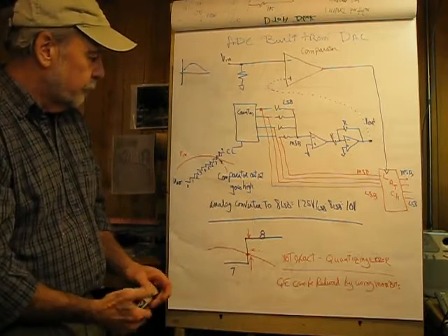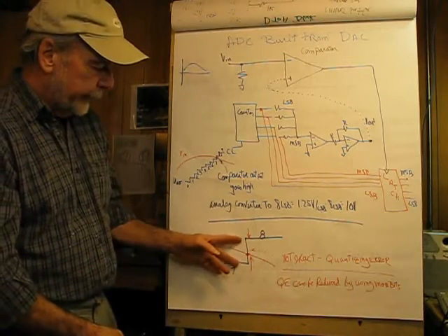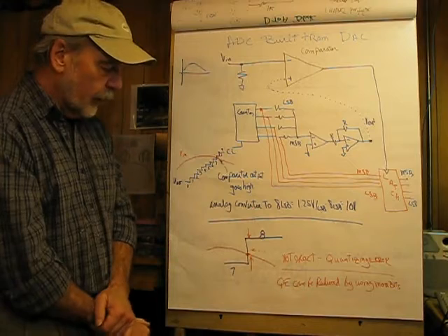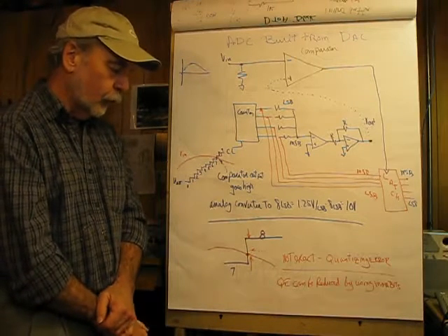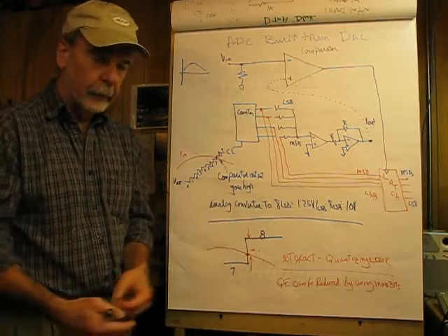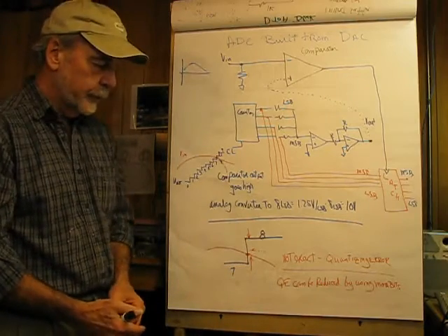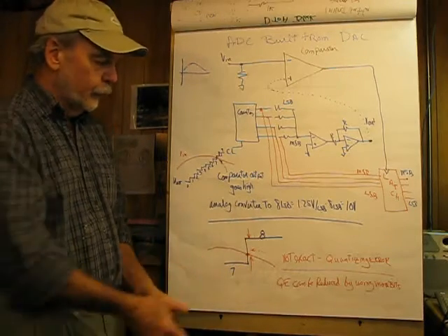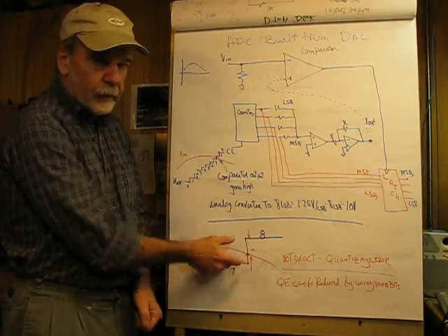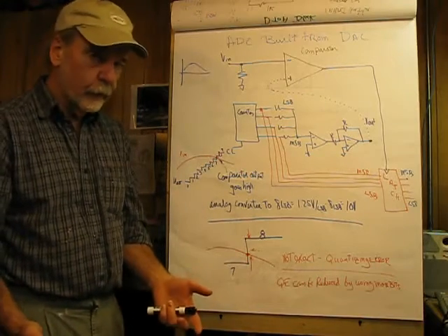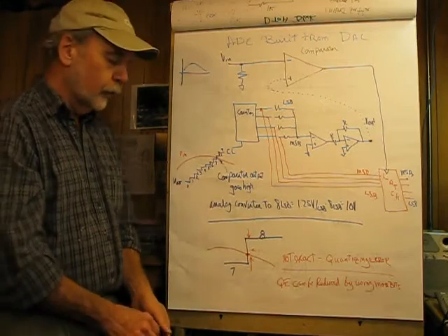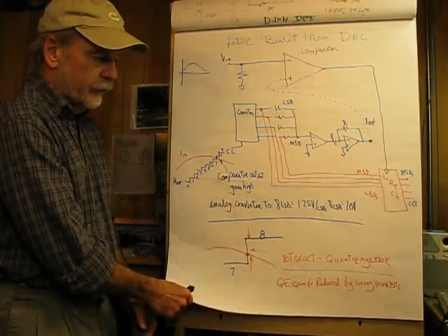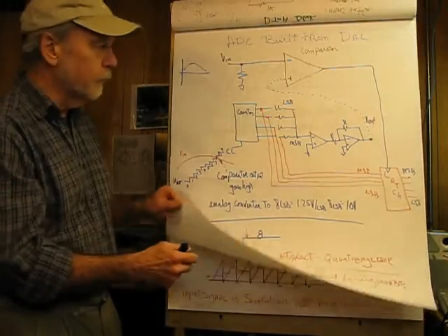So that would be the range of the quantizing error, between basically 0 and, for all practical purposes, 1 LSB. Other factors have to do with, is every step the same height? Well, no. And is every step the same width? No. So there's other considerations which we'll concern ourselves with later.